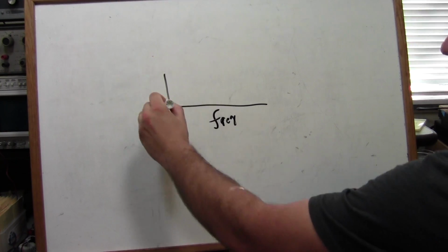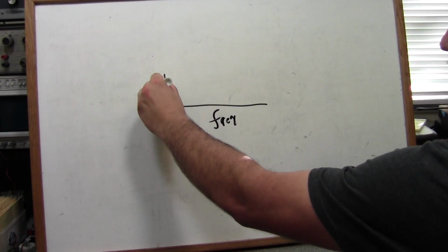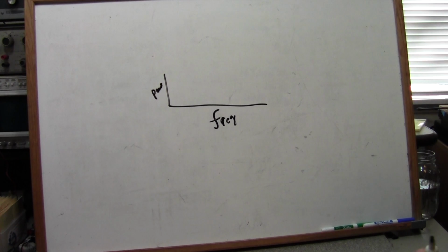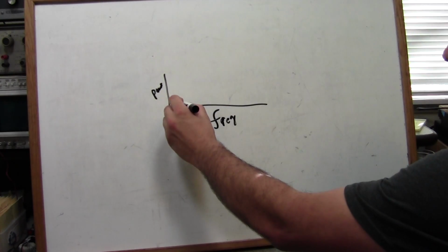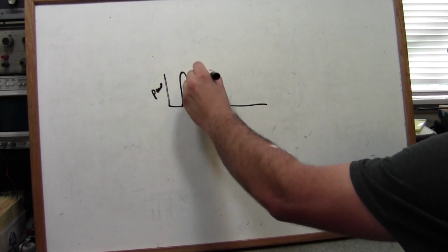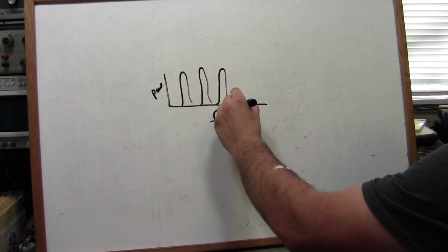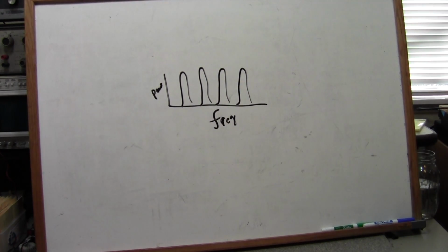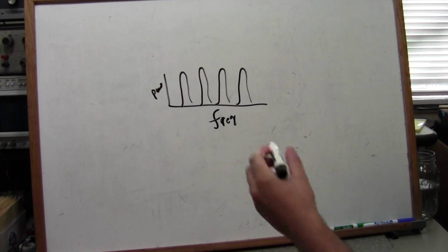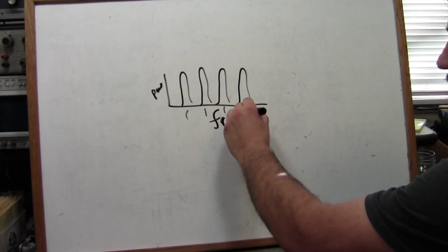Going back to the traditional channelized system that most people are used to, when you have multiple stations that need to communicate to each other, you allocate each one a fixed frequency that's far enough apart from each other that they don't interfere with each other. The problem is that it means that you have the high overhead that you need to administrate all these fixed frequencies, which are very limited in number due to their wide spacing.